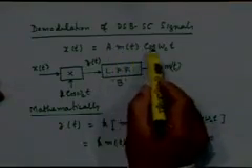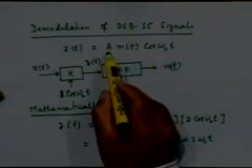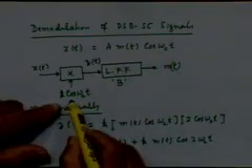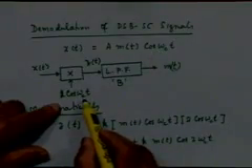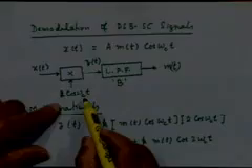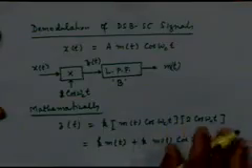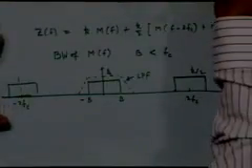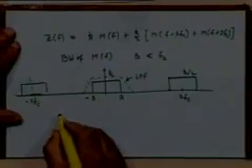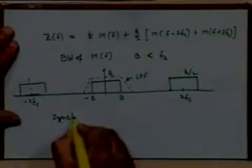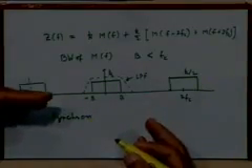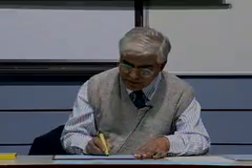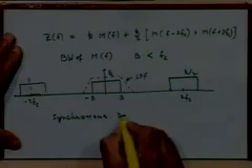The modulation was being done by multiplying m(t) with A cosine omega_c t, and we are assuming that a perfect knowledge of frequency and phase of this signal is available at the receiver, right? So that you can multiply it by a local carrier, a replica, and get your demodulated output. So implicit in this demodulation process is the concept of synchronicity between the transmitter carrier and the received carrier, and the local carrier of the receiver, right? So therefore this is also called synchronous demodulation.